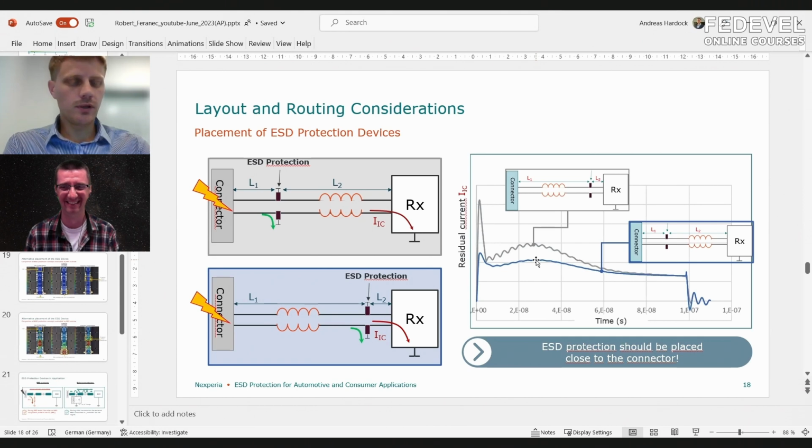Yes, in really risky layouts, you can control your ground current somehow, up to a certain point, and you should use this if you have a really sensitive PHY, where even a very small amount of current in the area of the PHY will impact it somehow, or can even damage it.